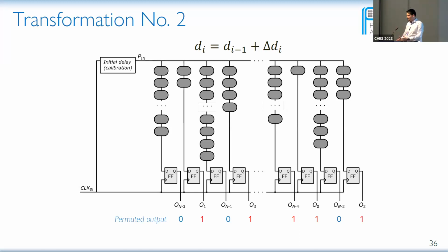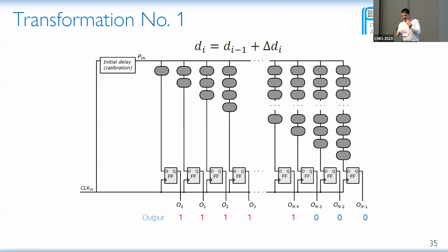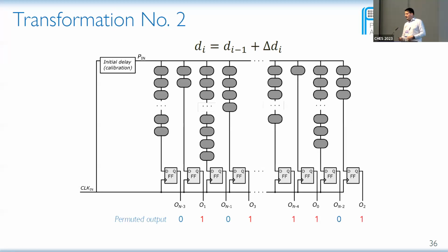Thank you. It's a very interesting question. The main part of the encoding of the output is just Hamming weight. So we sum the number of ones at the output. This means that the TDC, which has an order of ones followed by zeros, and this, which has 1 0 1 0 1 1 1, however it goes, when we sum it, it's still the same value. That's what we can see here. There's an order here, and here it's just permuted, but we still sum it.